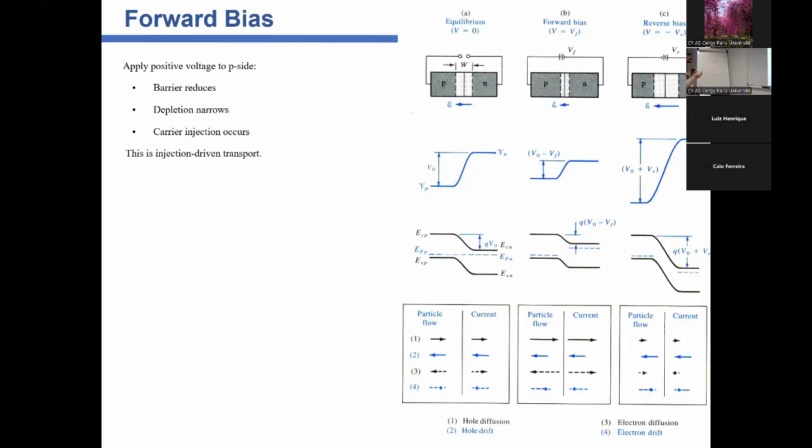of the electrical field coming out of the material that we are getting from the source, from the potentiostat, for instance. So this is the bias coming from the source, and this is the built-in bias, built-in electrical field. So depending on the voltage that we are applying, you can see that sometimes we can also have this flat band condition.